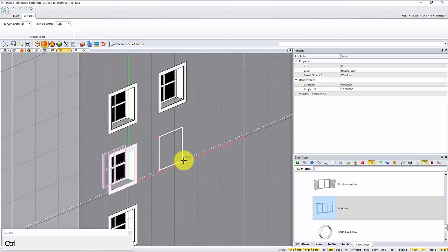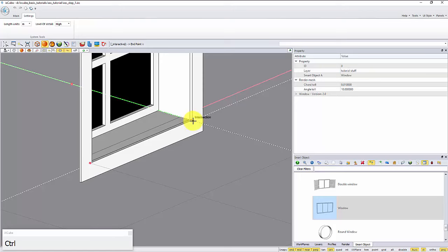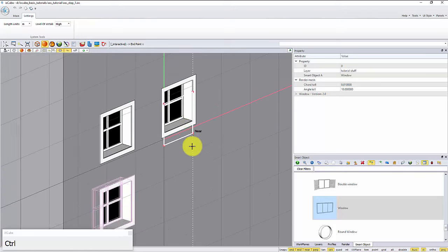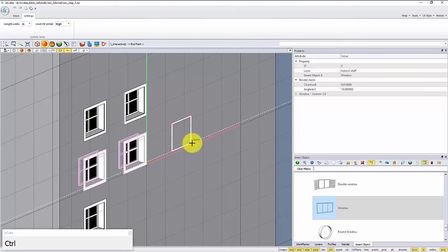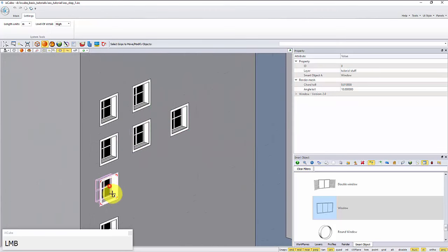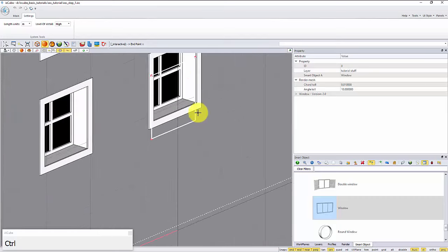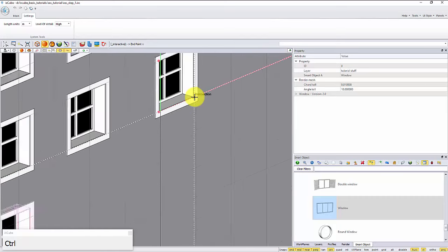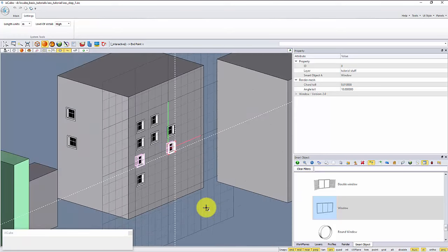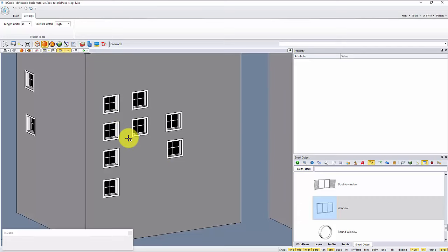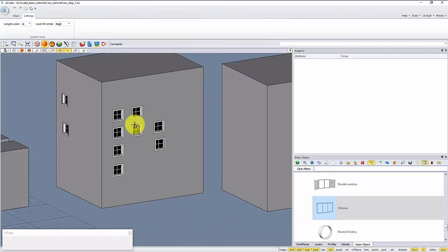If we want to align this window horizontally, we have this smart object, but we don't have the vertical one. But you can zoom in, you stay a little bit on this point, and the software gives you the horizontal and the vertical alignment, so we can drop another one. So I can move this, and now if I want to copy this horizontally, you can go here, keep the mouse over that point, and then snap to have an alignment.